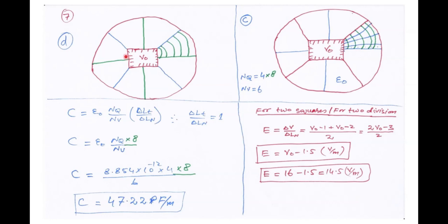For example, draw one unit cell in this way, then others of equal size one by one, and in this way you can fill the big flux tube, or the space in between two conducting boundaries, with curvilinear squares. You can either use this procedure in which we first draw the equipotential surface, or first draw the flux tube, then equipotential surface, and produce curvilinear squares in between the conducting boundary.